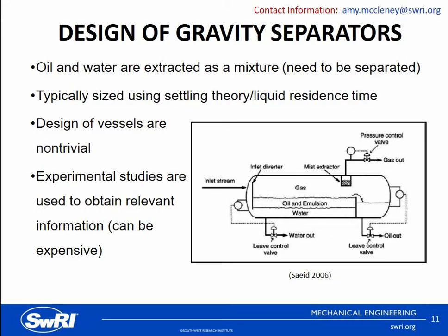Separator designs can employ analysis from bottle shake tests, experimental studies, and modeling. Shake tests involve fluids with realistic well properties put into a small container, shaken or agitated for a certain time, and then timed for gravity separation. These tests tend to be a little bit crude, but can give an indication of the needed residence time for separator sizing.